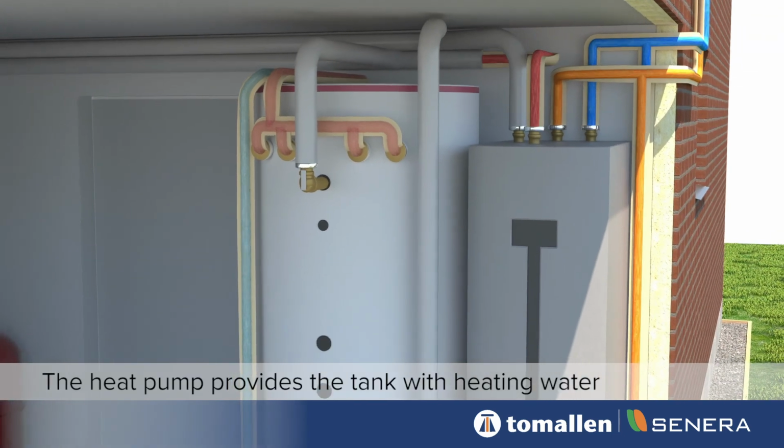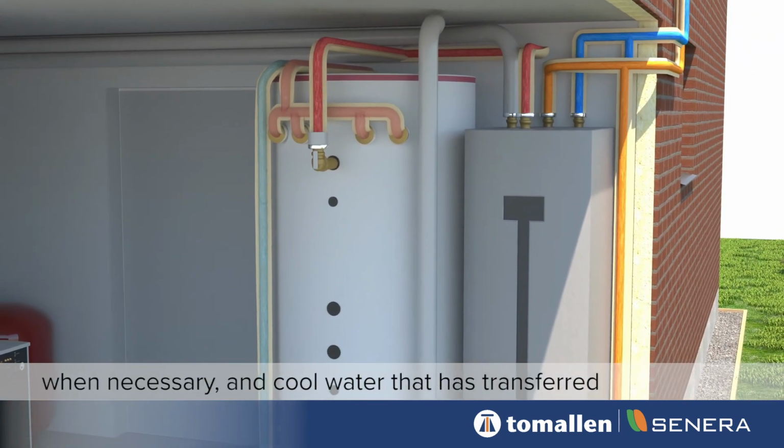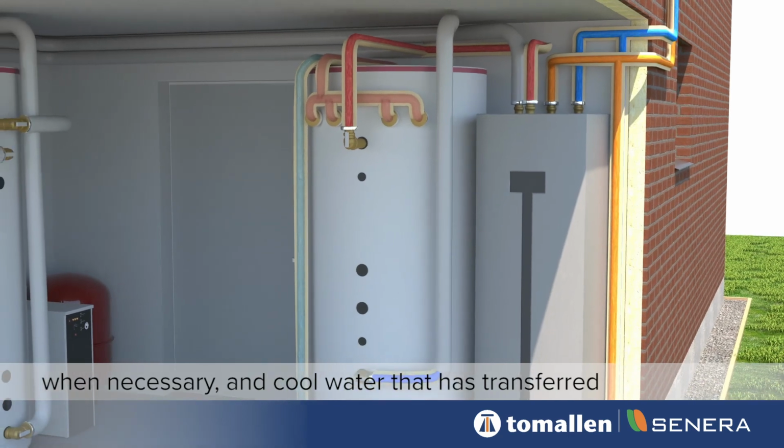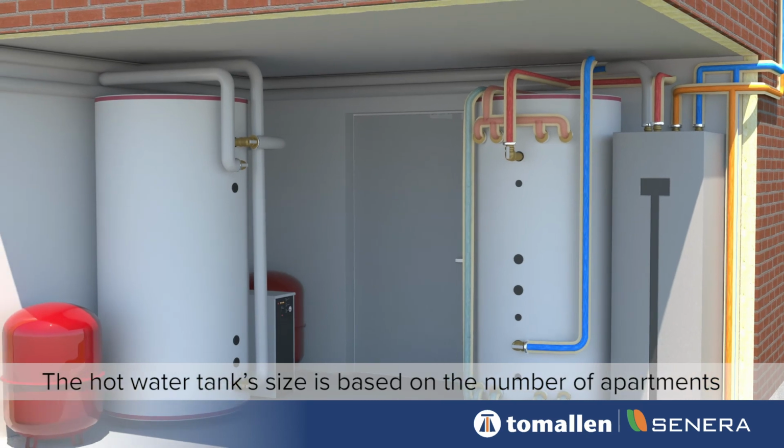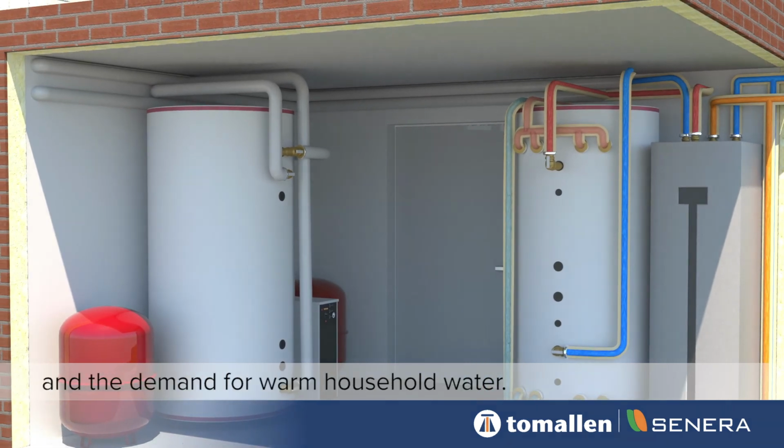The heat pump provides the tank with heating water when necessary, and cool water that has transferred its heat returns to the heat pump. The hot water tank size is based on the number of apartments and the demand for warm household water.